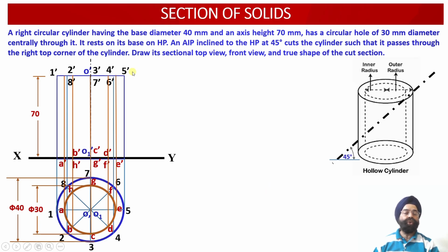One thing we must note over here, we haven't marked these 8 points corresponding to the outer cylinder on the base of the cylinder because of the symmetry. Similarly, the 8 points corresponding to the hollow section, we haven't marked at the top face over here, again because of the symmetry, because otherwise we would have got 16 points on the top which would be very close to each other, and again 16 points on the bottom face we would have obtained over here.